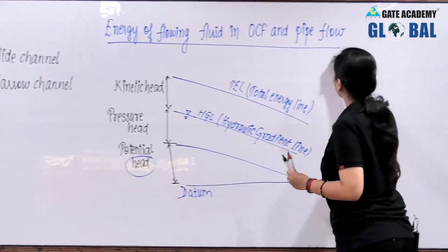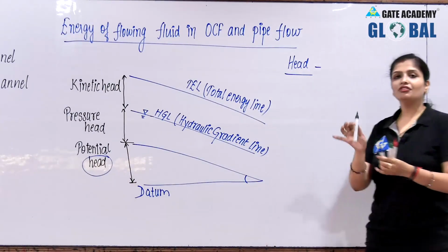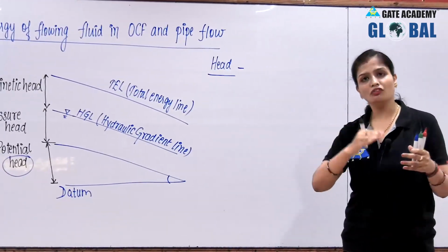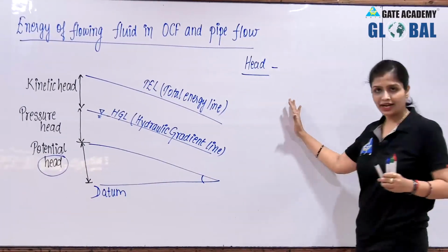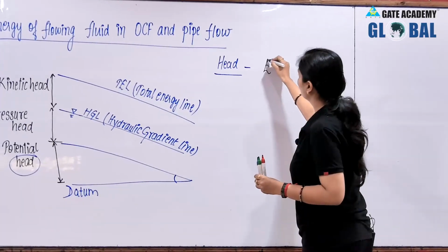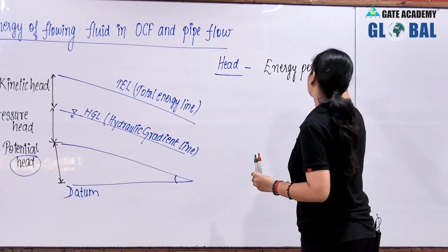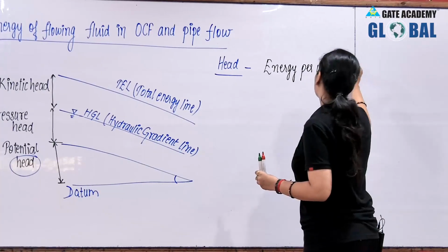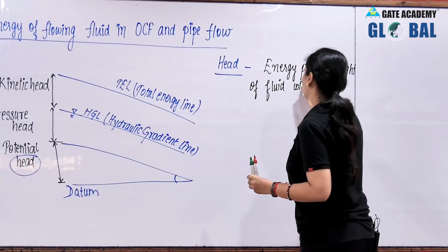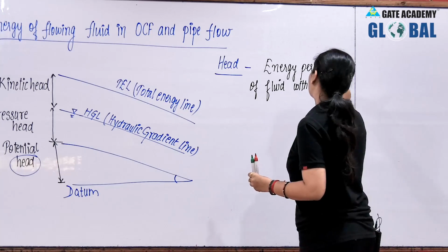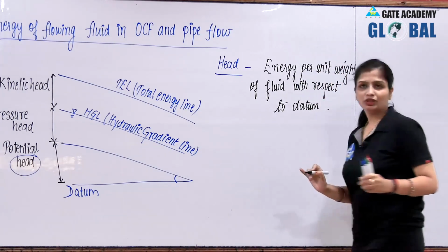So now I'll tell you. The meaning of head is energy. Whenever you take energy per unit weight of fluid with respect to any datum, then it is known as your head. Fine. What I said is energy per unit weight of fluid with respect to datum, this is known as your head.